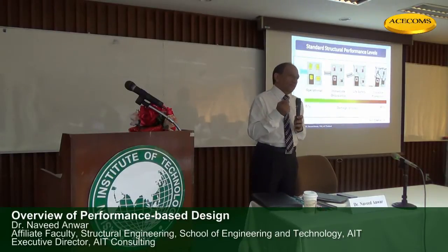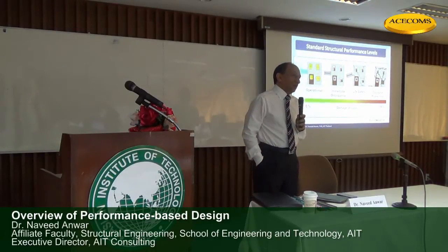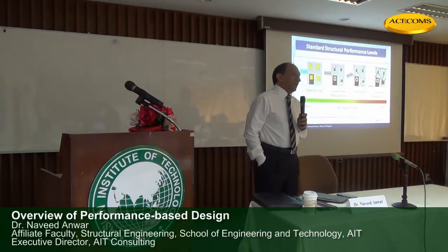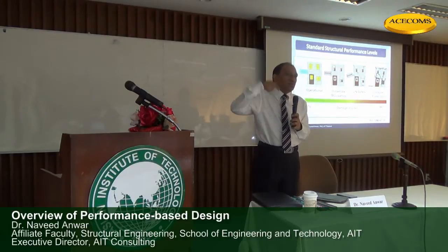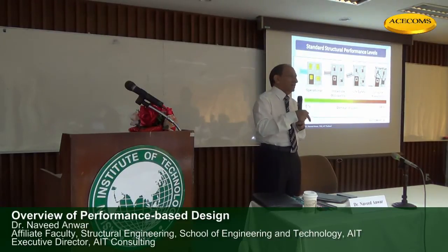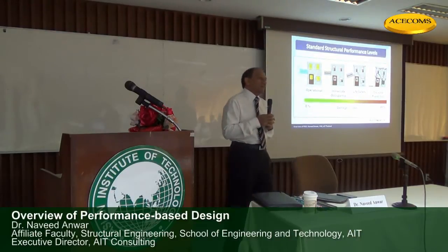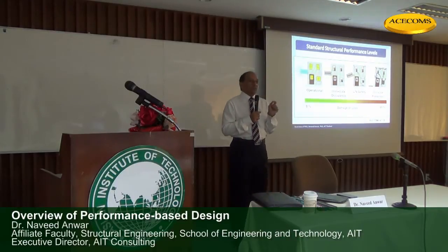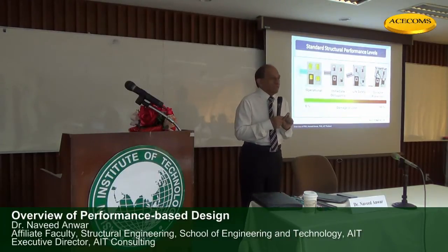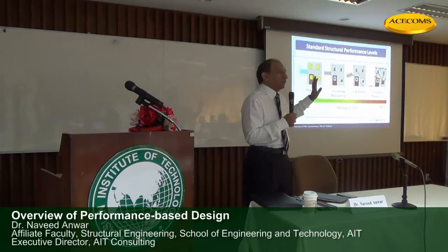Now please remember one thing, we will talk about capacity-based design tomorrow. The bending moments and shear forces do not cause collapse, it's the deformation that does. The deformation due to the actions is the cause, not the bending moments. So that means our concern is not the forces, but deformations. So all the limits in performance-based design are set on deformations. We don't care about what the force is.